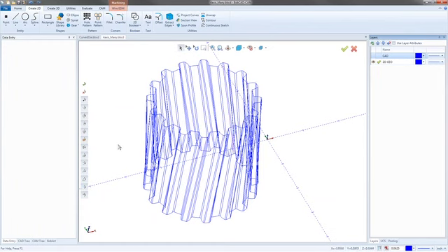So now there's a lot of these lines right through the center of this part that are definitely going to screw up my geometry selection. So what I want to do is take those lines and move them onto another layer. Now those lines, if you want to give them a name, are the sync lines.